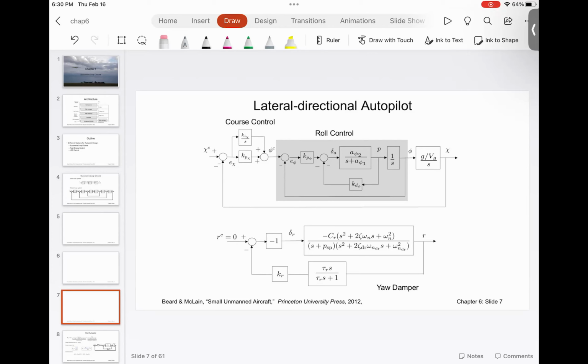So what I have is this equation. I'm going to take the Laplace transform. So I have x double dot, which becomes m s square x of s, plus c s x of s, plus k x of s is equal to u of s. Now u of s is the input, x of s is the output.